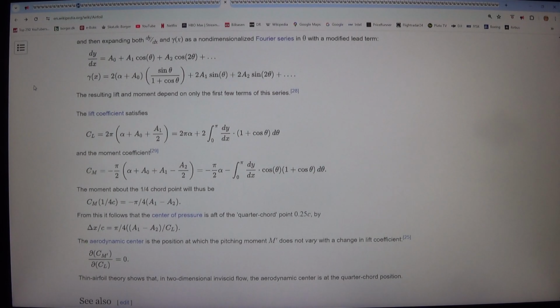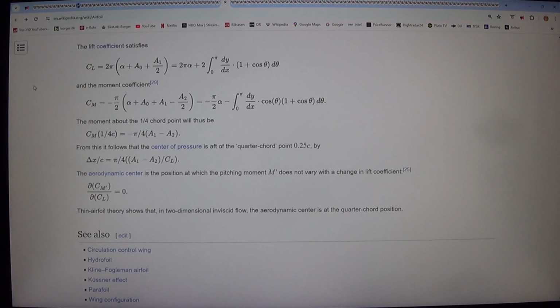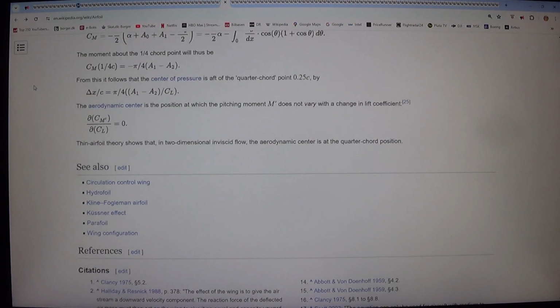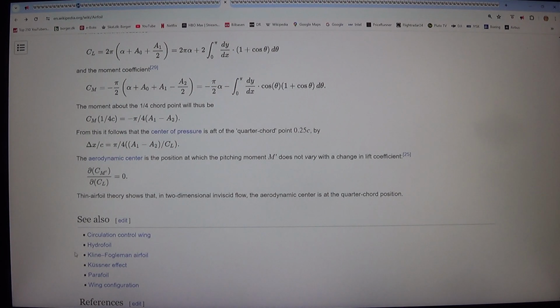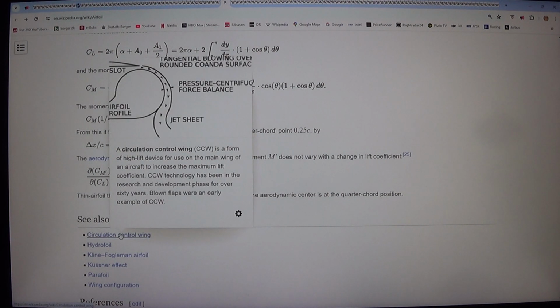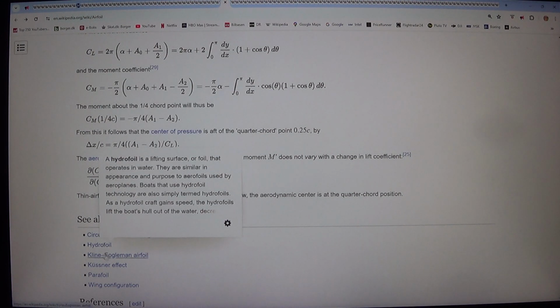Since the airfoil is an impermeable surface, the flow w(x) must balance an inverse flow from V. By the small angle approximation, V is inclined at angle dy/dx relative to the blade at position x, and the normal component is correspondingly dy/dx times V.